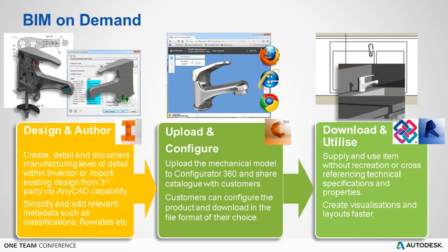as a BIM model. Now, as maybe a size A, size B and size C, to export those out to Revit, because of the complexity of the geometry and the manufacturing information, the only real option I have is to create 3 different models for that and then send them to Revit. So that's one way, and we can do that just as you saw with the air conditioning unit, or the staircase for that matter.